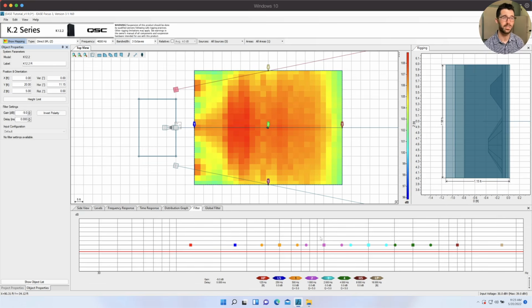I honestly don't touch this very much since I know the frequency response of most of the speakers I'm going to be working with anyway, and I fine tune that in the tuning phase. It's only if something is really wrong or different about a speaker I'm forced to use that I might correct it here, but I want to get everything as close as possible with placement, aiming, and array geometry before I ever start to touch EQ.